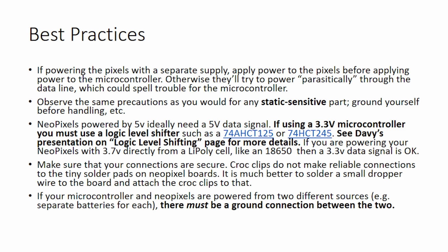Don't try, "I'm just going to connect this up with crock clip wires to see if it works," because connecting and disconnecting crock clips can cause little sparks, and little sparks are overshoots and undershoots, and they will kill a NeoPixel. Much, much better to solder a wee wire on and then crock clip to the wire than to try and crock clip to the board.